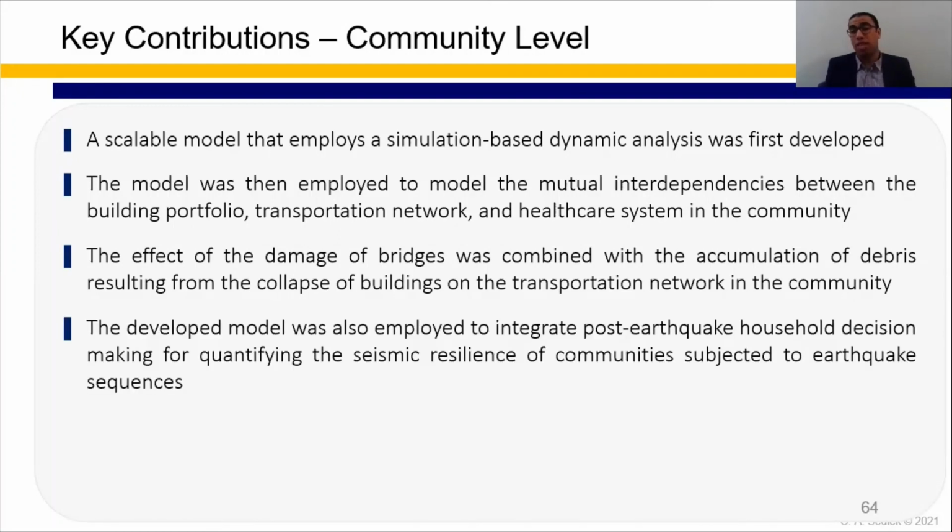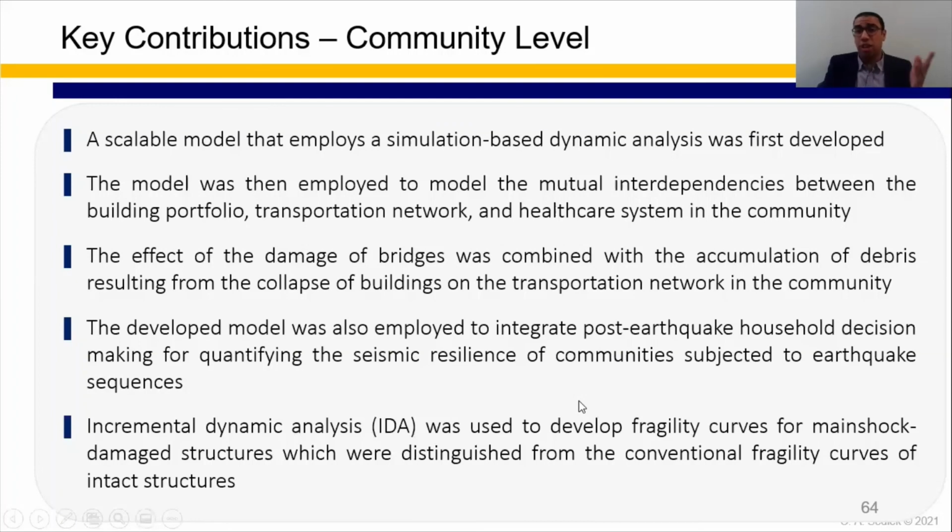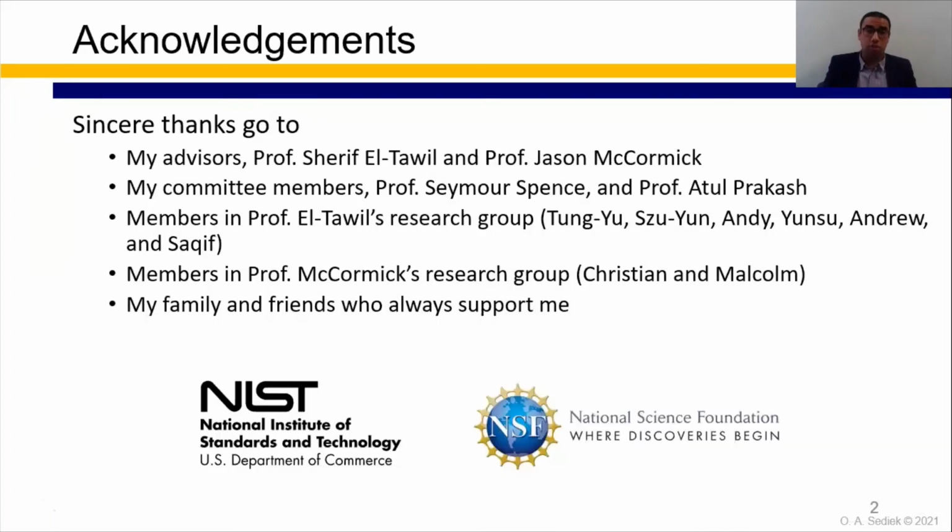Also, the developed scalable model was employed to integrate post-earthquake household decisions in quantifying the seismic resilience of communities subjected to earthquake sequences. To this end, incremental dynamic analysis was used to develop new fragility curves for main shock damaged structures, which were distinguished from the conventional fragility curves of intact structures.